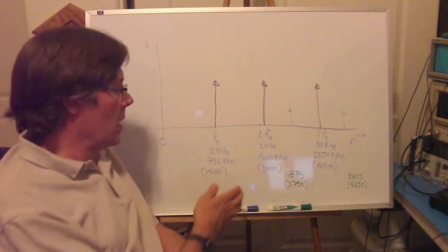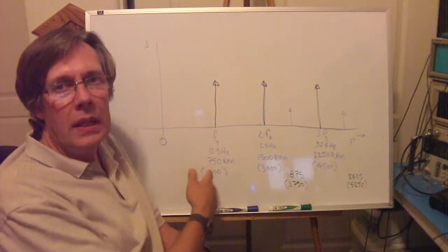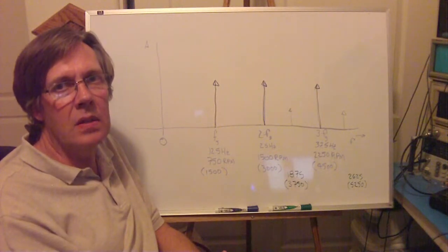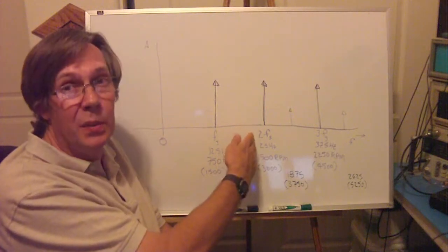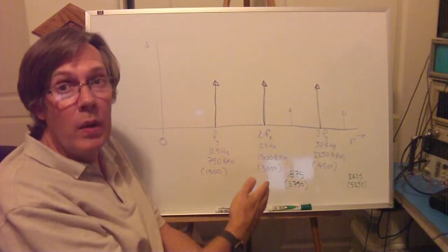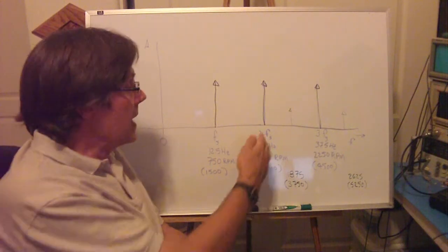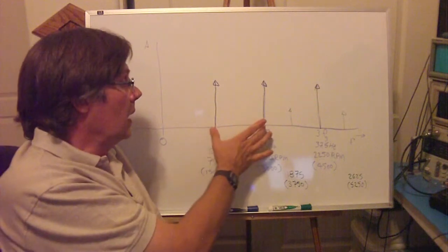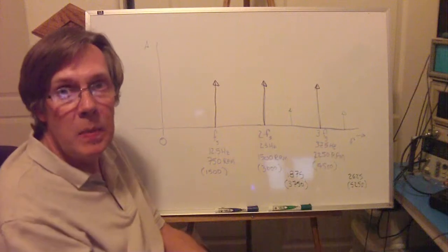these frequencies. Now, when we're actually running the helicopter, it can't turn this slowly. It basically shuts off instead of being able to control the speed down that slowly. When it comes on, it's turning at about 1,300, 1,400 RPM. That's kind of why we chose 12.5 samples per second, 12.5 hertz for the strobe rate, so we can catch this whole, what we call ambiguity region, or region between where it looks like it's doing the same thing, where the aliases repeat, so to speak.